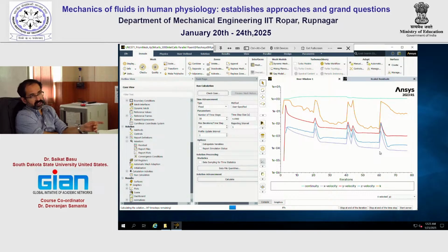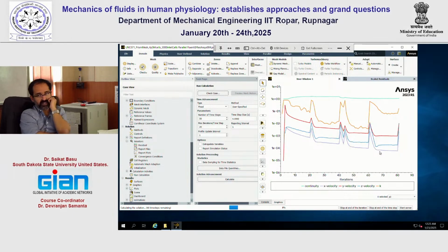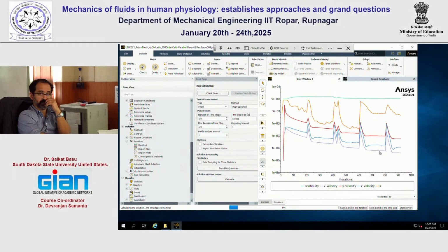But you are trying to simulate the whole inspiratory phase. That has its importance, maybe for heat transfer, but not for particle transport. On the other hand, if you develop a two-phase simulation where the particles can impact the flow field, then you should probably think of it as a 5 second flow or a 2.5 second flow for the inspiratory cycle and see where the particles go with that. Because now it's a two-phase system, right? Does it make sense? But then again, the computing demand would be much higher. So something to think about in future.